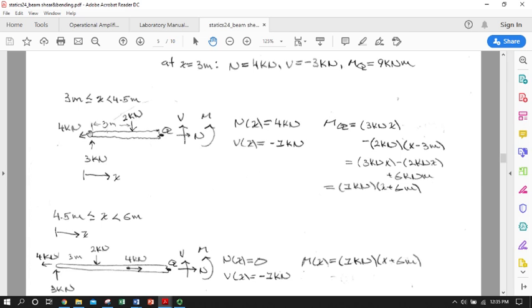So we integrated separately the effect of both of these point loads to get an expression. And we can show that we could have just integrated this effective one over some limits of integration, but we get the same expression. We end up with the moment at point Q anywhere as being 1 kilonewton times (x plus 6 meters).